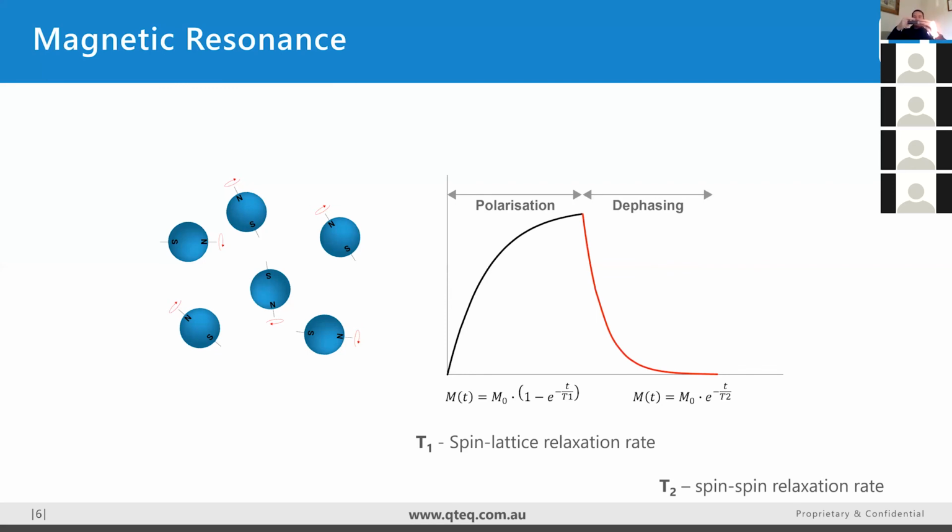Have you seen that in the image? If we do the harmonic mean, you end up taking the inverse of the values that you're averaging. So a low permeability zone will have a bigger impact. So water going in a vertical direction, if this is a low permeable barrier, will be driven by this.